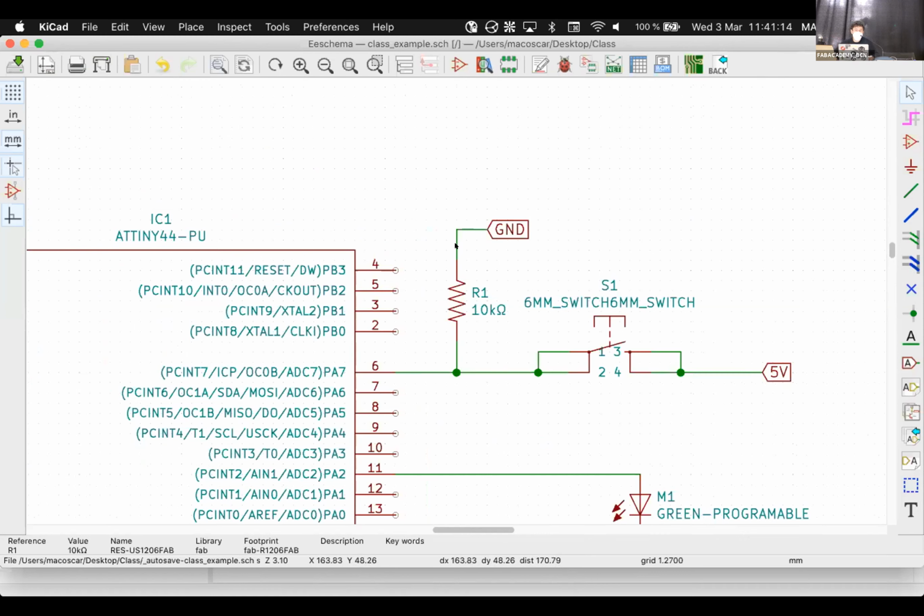Exactly. Here, in this situation, if I press the button, I don't have a short. And that's why I put a very high resistance value. It's 10 kilo ohms. Of order of magnitude, everything over kilo is very large. Everything below 100 starts to be complicated. You'll see that it warms up.